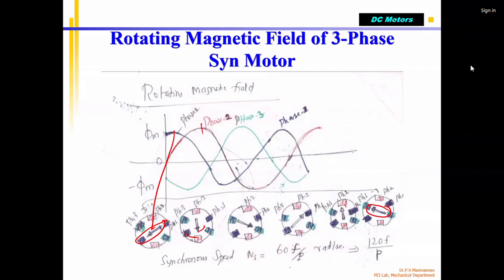So how is it? The rotating magnetic field attracts the rotor, with north and south poles, which is a permanent magnet. You know that the north pole attracts the south pole, correct? So the south pole attracts the north pole. So the magnetic fields get locked. We say that initially, in a synchronous motor, when you give the AC voltage through 3 phases and the rotor the DC voltage, the rotor may be somewhere, in the middle position also. But first it has to get locked with this, correct?